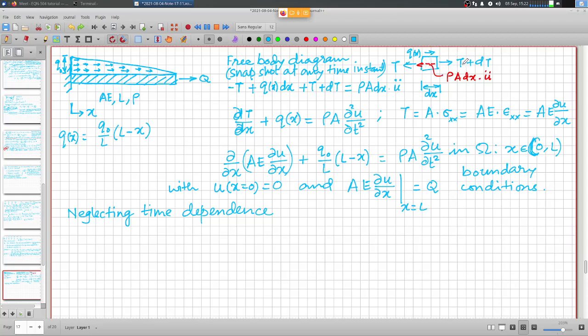So these are all the forces we consider acting on this differential element that hold this particular differential element in equilibrium at any instant of time. So the whole idea of using this fictitious inertia force concept is that you can extend the concept of static equilibrium of forces acting on a body to the dynamic situation. Otherwise, you need to look at Newton's second law of motion, the law of momentum.